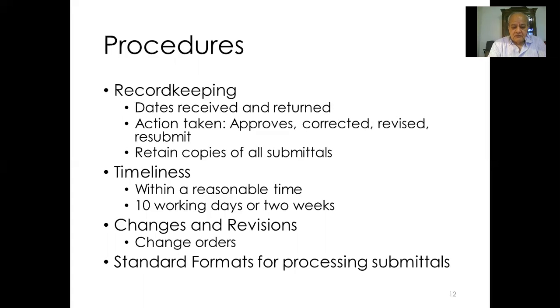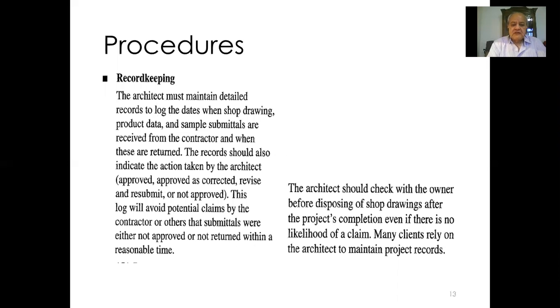Any change or revision should be done through a change order, not verbally. Everything must be in writing, because this is money. So any change order must be approved by the owner and submitted to the contractor through the owner, because this will be translated to extra money paid by the owner. So you have to have standard formats for the letters, for the correspondence, for the record keeping, and so forth. So as you said, record keeping is extremely important. Keep records of everything.